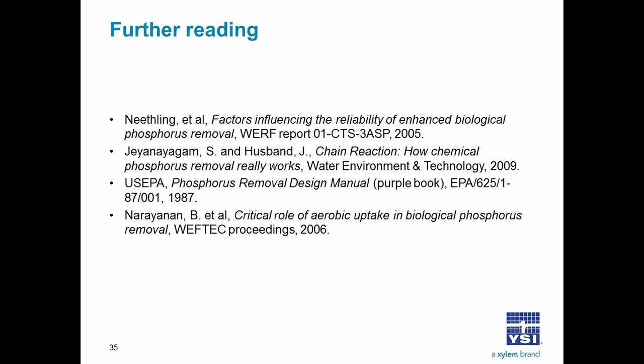Well, I guess the ultimate measure is the effluent total phosphorus. But as far as in the process goes, if I understand the question correctly, with chemical, it's the process monitoring, and of course, if you use a feedback strategy, you will have a phosphate measurement downstream. With biological, you've got two things to measure, and that is the phosphorus release and the phosphorus uptake.